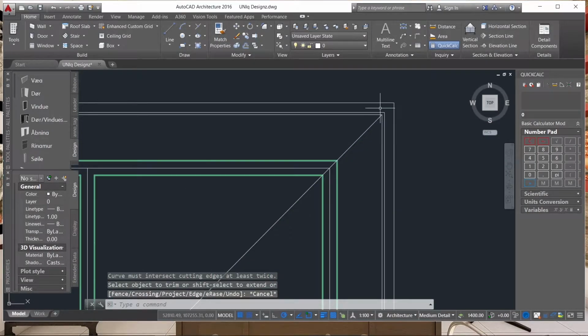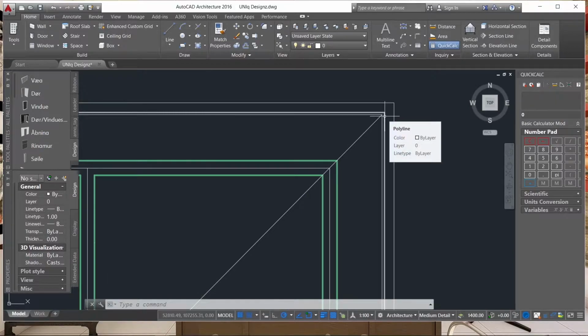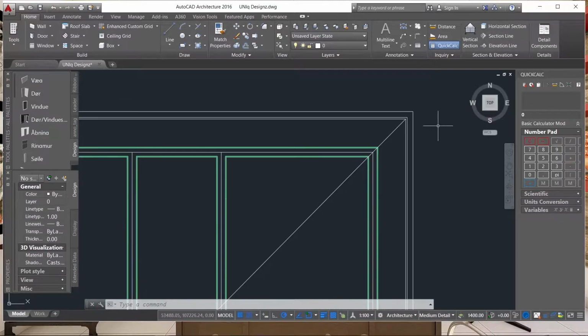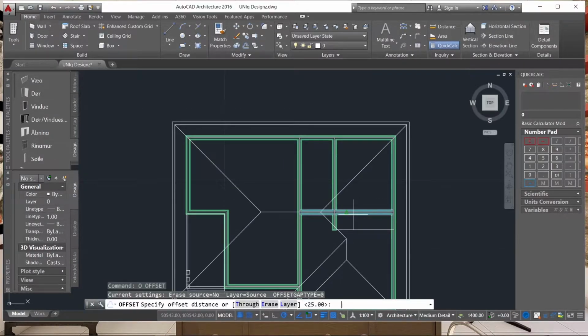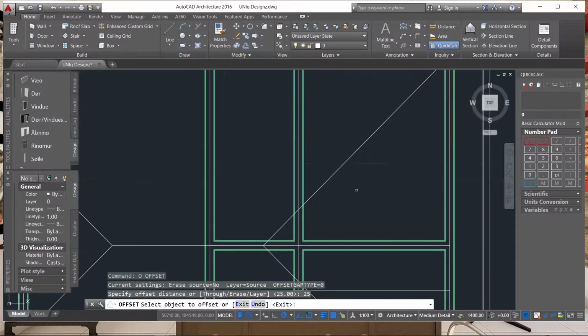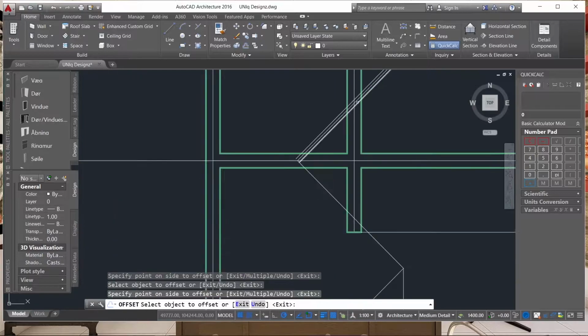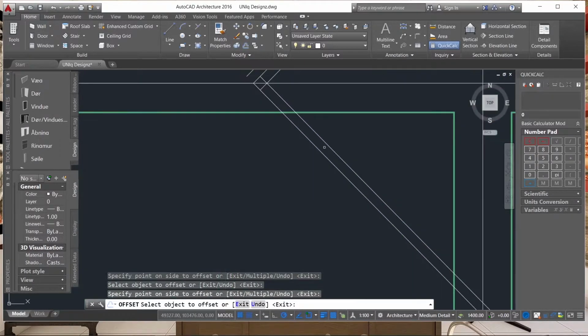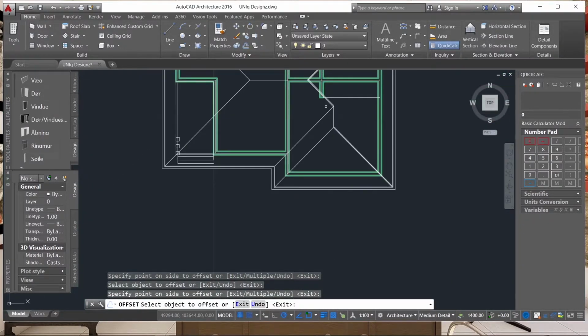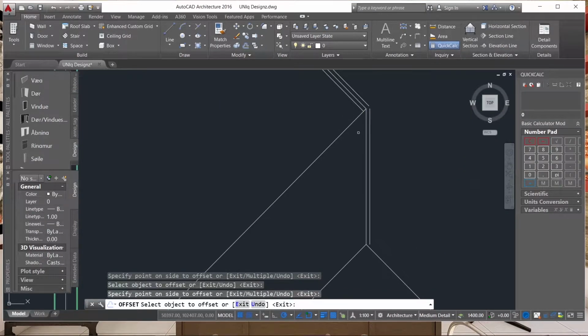After we are done with drawing the fascia board, let's move on to drawing our ridge. After drawing our ridge, we move on to drawing our rafters. Then we end up with the purlins. Starting with the ridge, activate your offset command with a distance of 25 millimeters. Then offset all the ridge lines from the center to the left and again to the right.